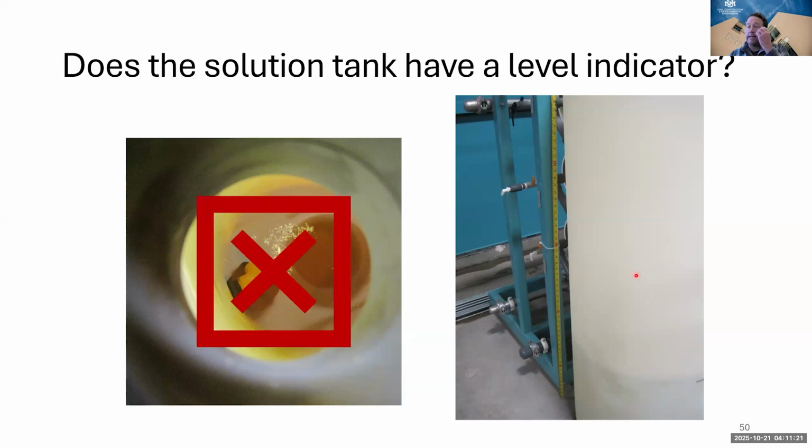Instead, what we like to see is some sort of measuring stick or some sort of marks on the tank that show what that level is. This system took an old tape measure that had broken, went ahead and zip tied it right next to the chlorine tank, and every day they write down how much chlorine they've used, and they know exactly how much chlorine is in that day tank.